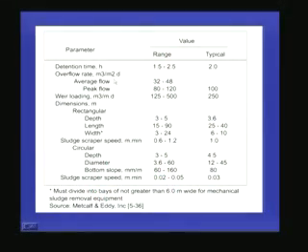So, these are the typical values of a primary sedimentation tank which is commonly used in wastewater treatment processes. The detention time varies from 1.5 to 2.5 hours. As we discussed earlier, if the detention time is higher, what will happen? The organic matter that has settled at the bottom of the tank starts degrading anaerobically, and that generates gas. That gas will create turbulence in the sedimentation tank, and it will affect the efficiency of the tank. And the overflow rate varies from 30 to 48, and weir loading is in the range of 125 to 500. And these are the dimensions of the tank.